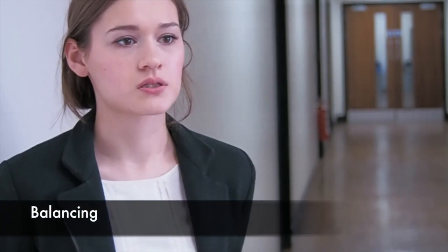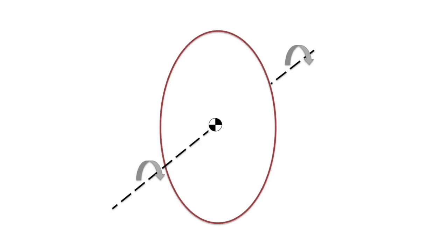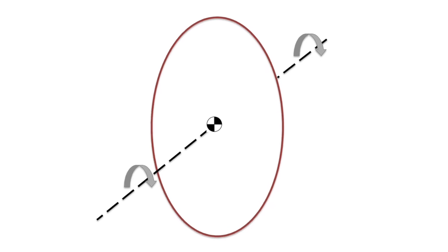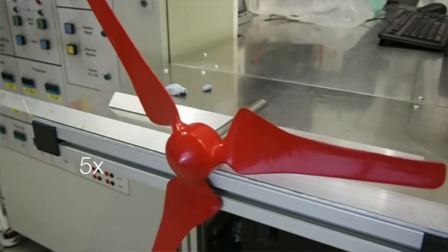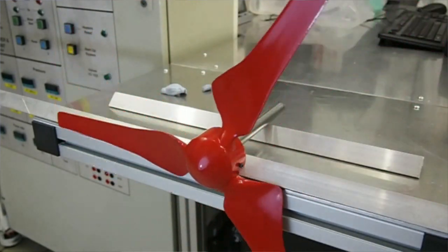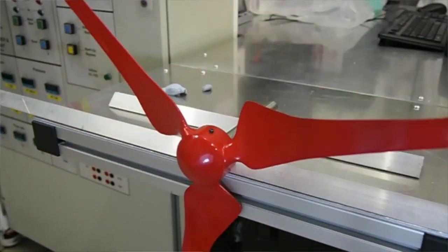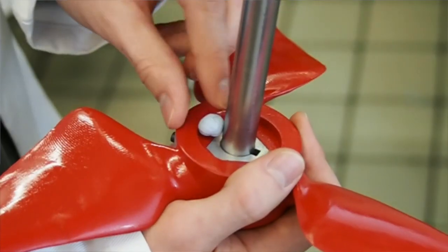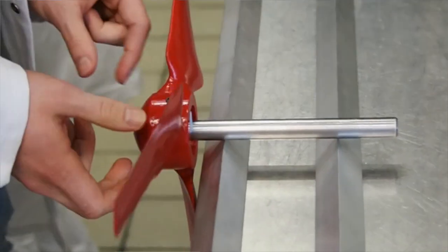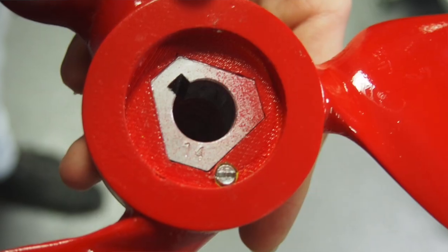Finally, to reduce inefficiencies related to out-of-plane wobbling due to misalignment of the turbine's centre of mass and the axis of rotation, we used the following technique to balance it. The turbine was repeatedly spun over a horizontal two-point contact to statistically determine the most common settling position. Correction weights were applied to improve mass distribution until the turbine showed no bias towards any position.